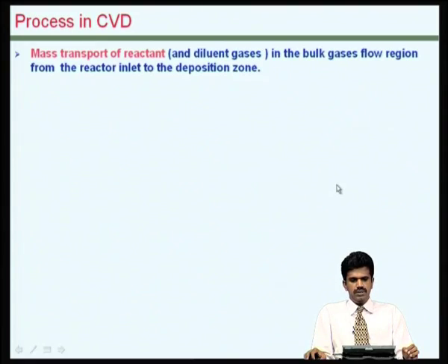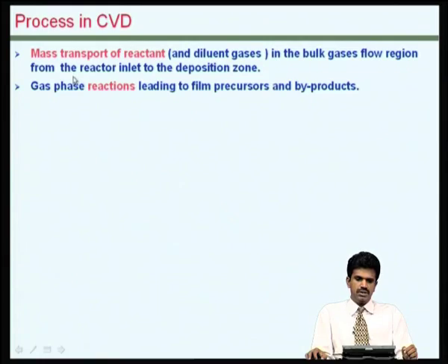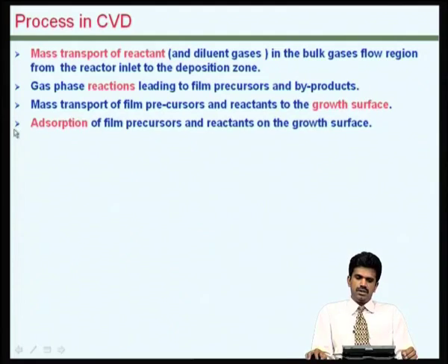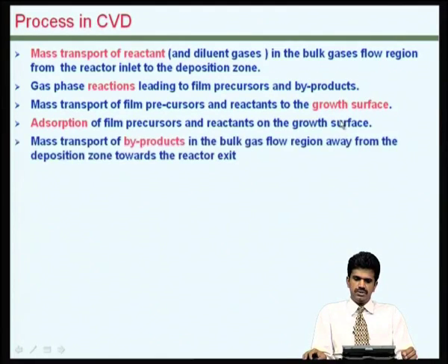In chemical vapor deposition, on the other hand, the reactant gases are transported into this chamber, and we make sure the chemical reactions happen, and the film material is essentially coming out of the precursors that are there in the carrying gases, and the film, which is the product of the chemical reaction happening in the gaseous form, is absorbed onto the surface, and also we need to make sure that the other byproducts of the chemical reaction could be carried out in the gas flow.